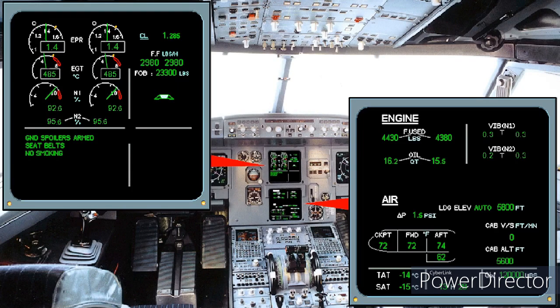Any of the conditions just mentioned can cause a compressor stall to commence, and as soon as it does, there is a partial breakdown of airflow through the engine. The indications of compressor stall can be any or all of the following. Fluctuations in the engine RPM. An increase in the vibration level of the engine, which can generate noise, which may become audible in the cockpit, depending on whether the engines are wing-mounted or rear fuselage-mounted. And an increase in the exhaust gas temperature, otherwise known as EGT.